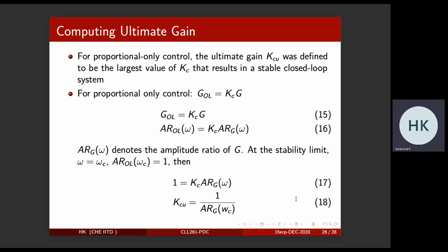controller design. I'm saying just look at the case when you are looking only at the proportional control, because you have your Ziegler-Nichols and Tyreus-Luyben and all those things ready. The table is essentially based on the fact that you do the field experiment based on the proportional controller. So let's keep the proportional controller, assuming that you have it installed in the system.